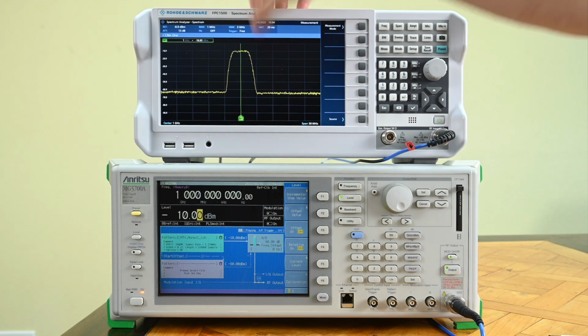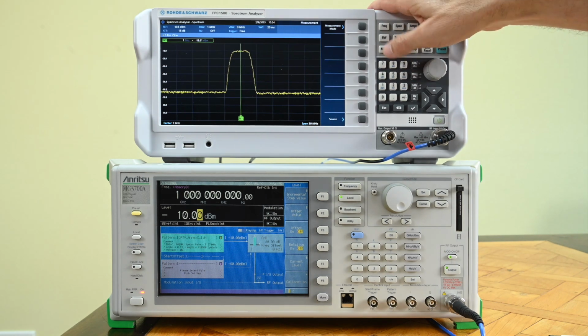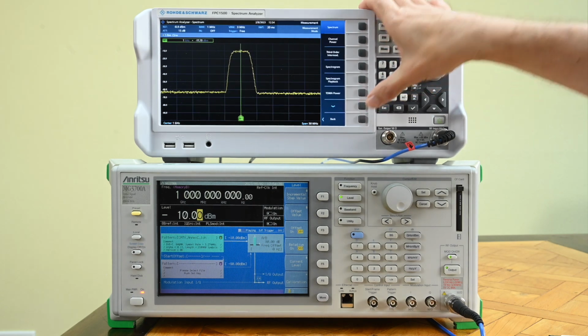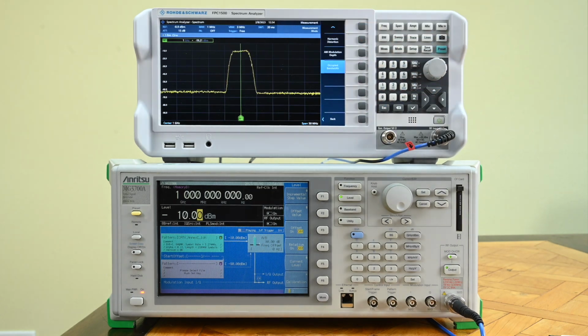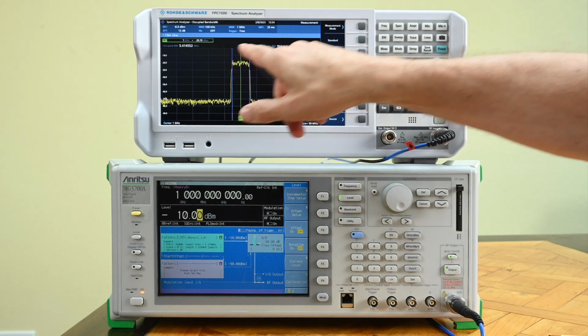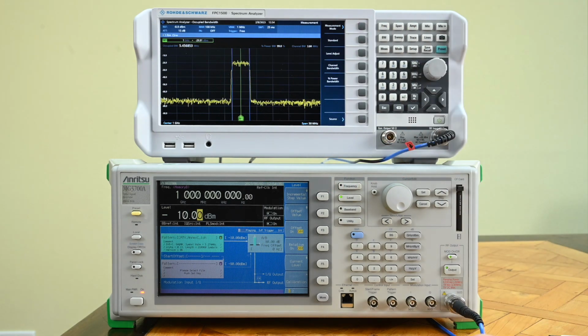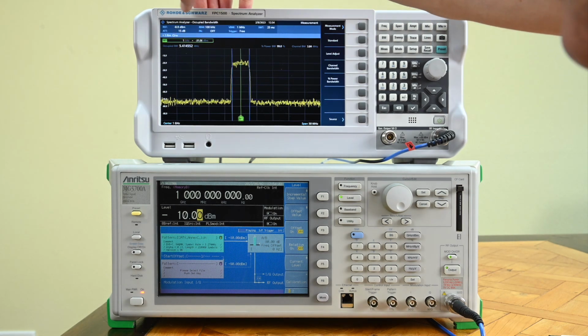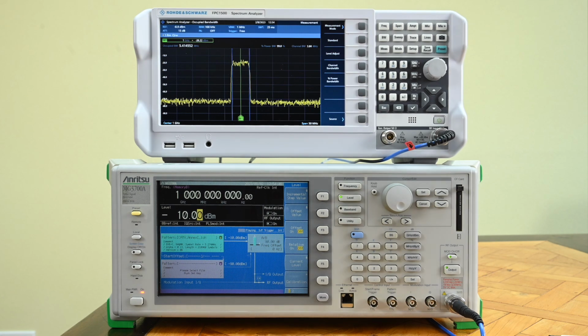Looking at the automatic measurement of bandwidth of the device, that is actually implemented here in measurement modes, and we've got an occupied bandwidth. You'll see it's the same signal. It optimized some of the settings for this specific type of measurement, and we now get to see the bandwidth is about 5.5 megahertz. Why do I say about?